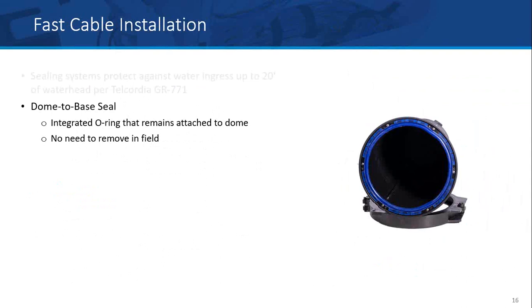A lot of the fusion splicers, I've met a lot of you guys and you're very proud of your work. Most fusion splicers I've met take pictures of the final quality audit of the closure. Well, then what happens down the road when somebody else goes to maintain that network? It destroys all that hard work. They forget to put the O-ring on, and then you get water ingress issues, again the freezing and everything else.